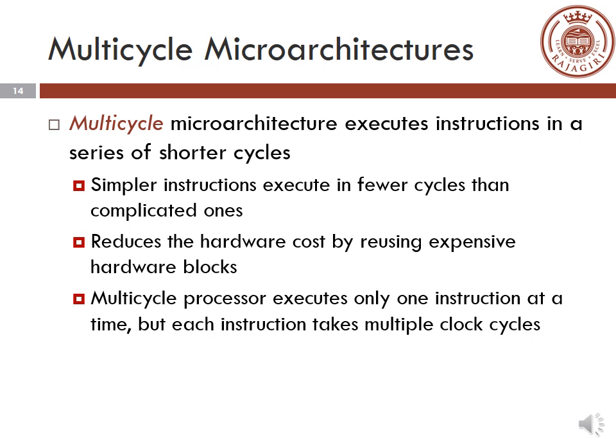A multi-cycle processor executes only one instruction at a time, but each instruction takes multiple clock cycles. So the processing of one instruction at a time remains as such, but the instruction can take multiple clock cycles. That's your multi-cycle microarchitecture.